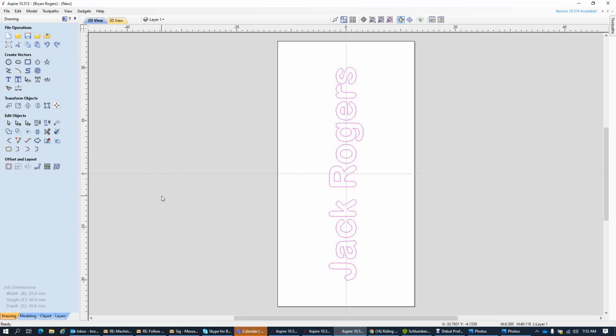And again, it doesn't really matter how big my work size is, because it's only going to carve out your name, and it's going to start from wherever you called 0, 0. That means you could put 0, 0 anywhere. You could put it on the handle or at the blade area, as long as you say, this is where I want the center of my carving.